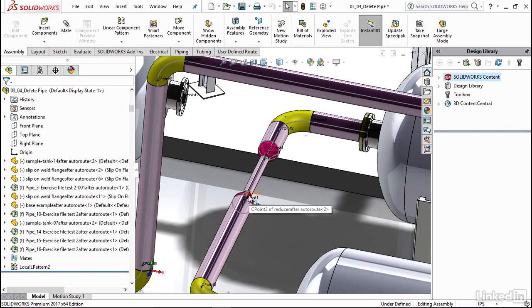Now that you can remove pipes when needed for your design, as well as update your route changes that will occur in your assembly, you're good to move forward onto our next step, which is going to be checking out our route bounding box.